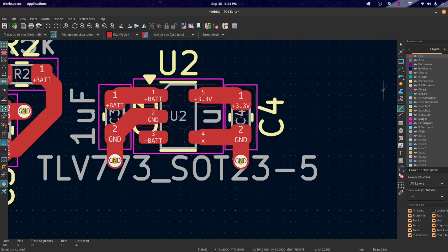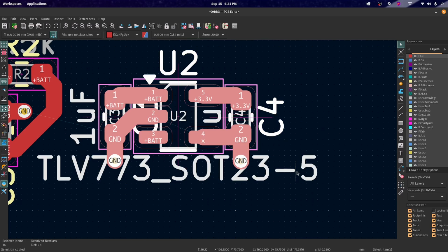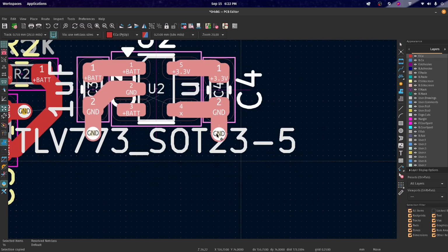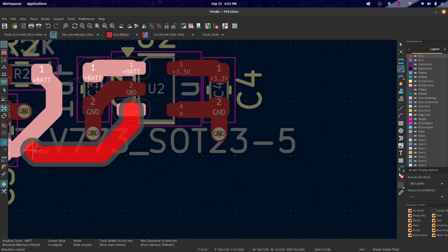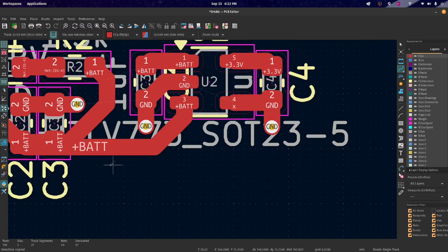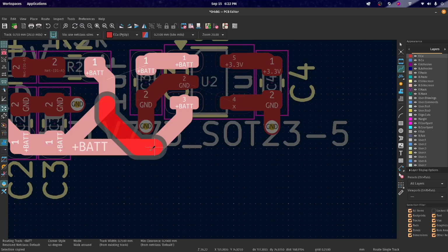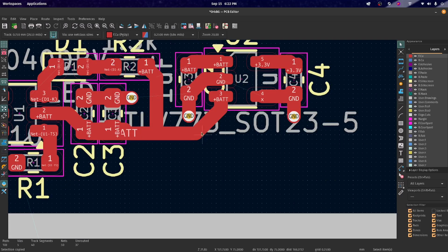But for me, I'm just going to play it a little bit safe, and let's say I connected the enable pin incorrectly, and it should go to low voltage. If I connect it like this, I give myself an out basically where I can cut this trace, and I just clean this up a little bit. There we go.